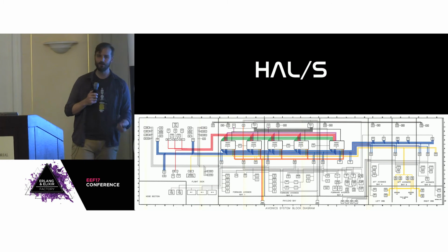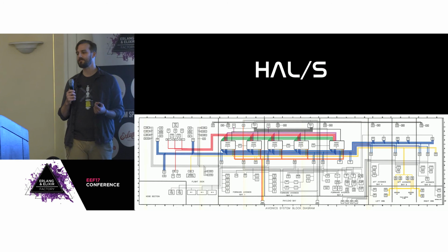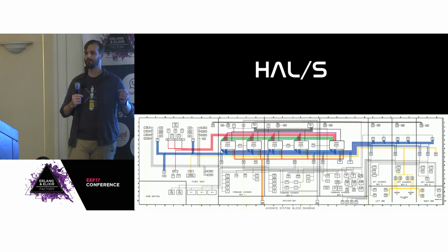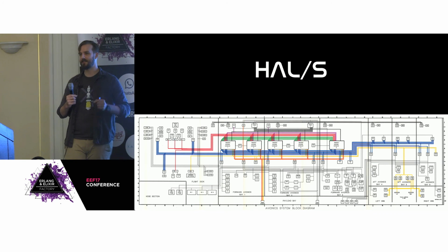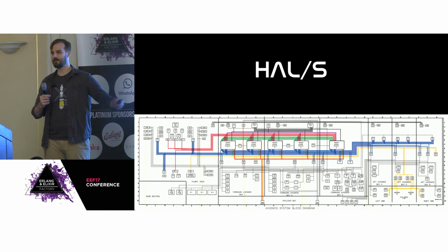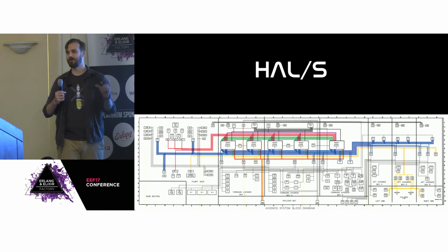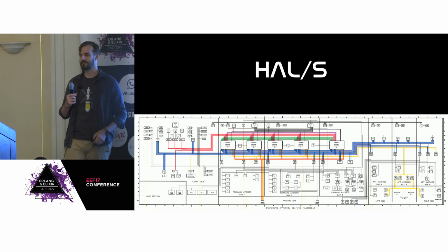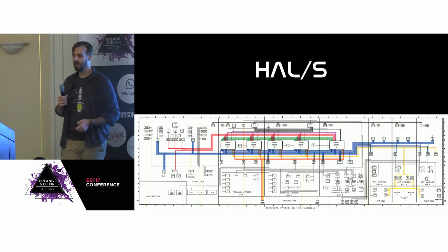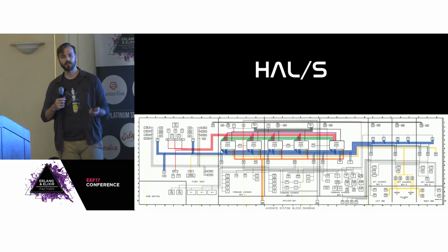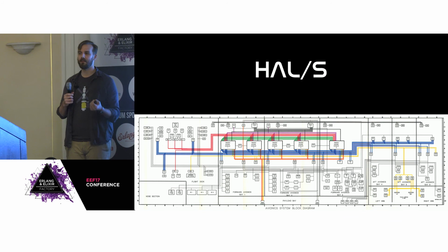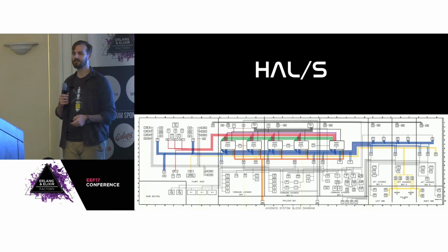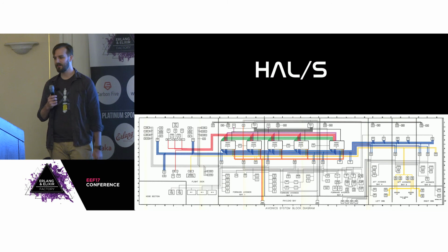So what was cool about HAL, if you had a computation that was supposed to last for just 10 milliseconds, you would put it in a block that was just a 10 millisecond block. And then if it didn't execute in that 10 milliseconds, it would cause an exception, and so on. But it would be concurrently in parallel scheduled with other blocks. And then the GPC would figure out how to schedule these things according to priority and according to time, which I don't know of any other language that exposes that particular style of interruptive priority real-time scheduling other than HAL/S, which now that the shuttle is grounded is a dead language.